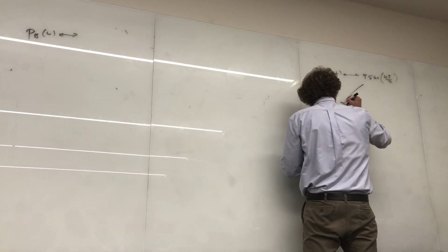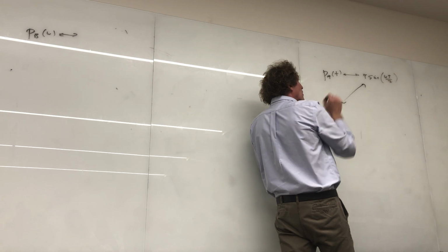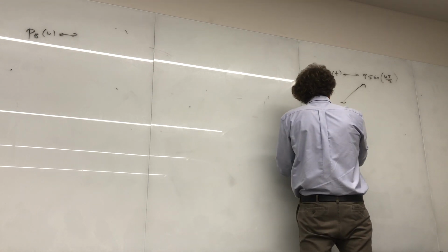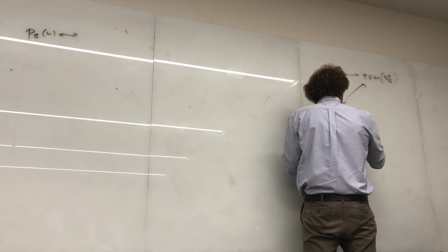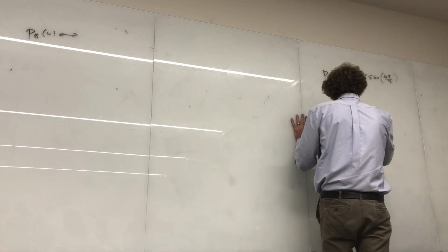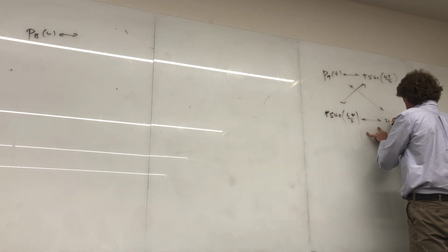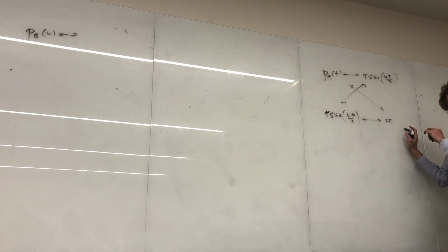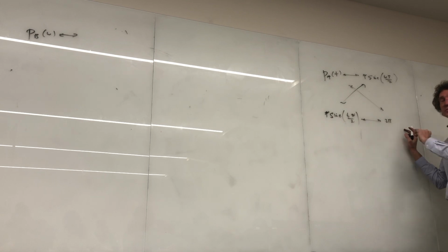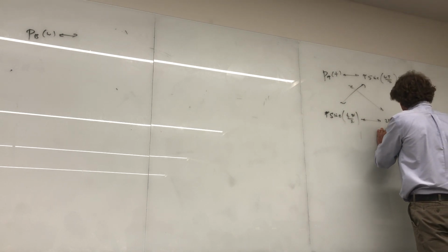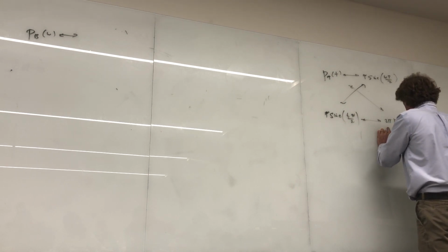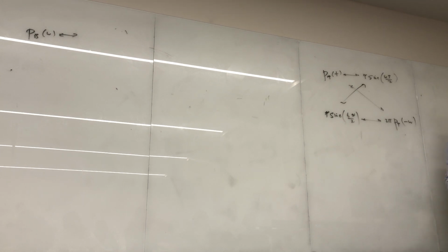Now we use duality. We take the mathematical form of the transform in the omega domain and replace omega with t. So it's tau times the sinc of, now it's going to be t tau over 2. And here, now I'm going to get 2 pi. Don't forget that 2 pi right off the bat. If we were using a transform that was defined in f, you wouldn't need that. But here, you've got to have the 2 pi. And then you replace t with minus omega. Make sure you're used to writing minus omega. We know we're going to make it plus omega. Just get used to writing it, okay?